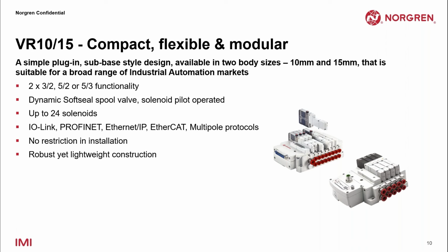When you compare a valve manifold to individually wired solenoid valves, manifolds offer various benefits. First, they provide a neater solution and occupy a much smaller footprint. The time and effort required to install and set up a manifold is much less than installing and connecting multiple solenoid valves one by one.